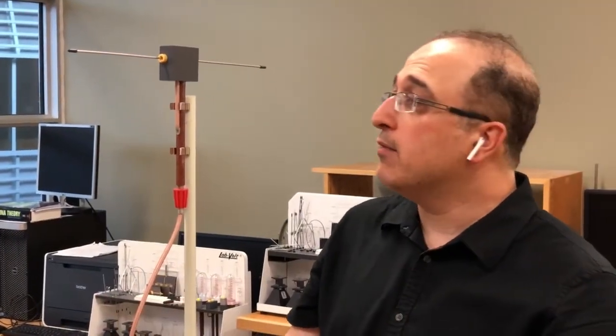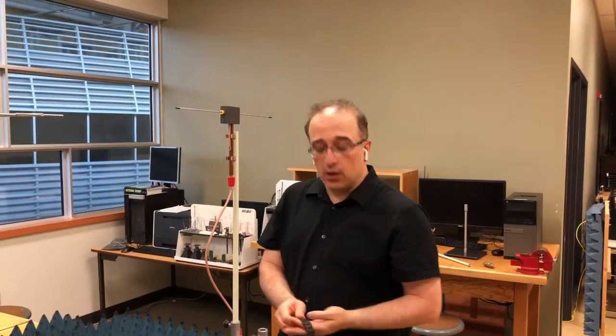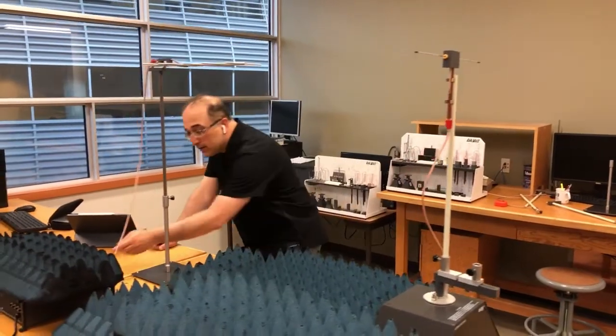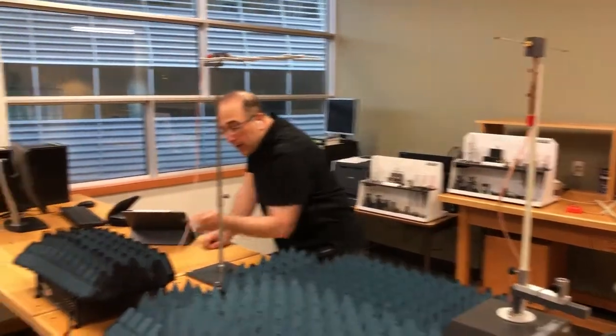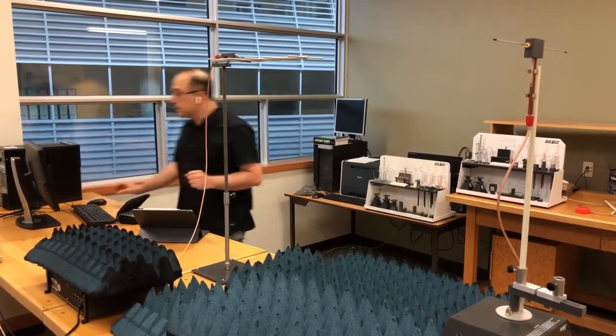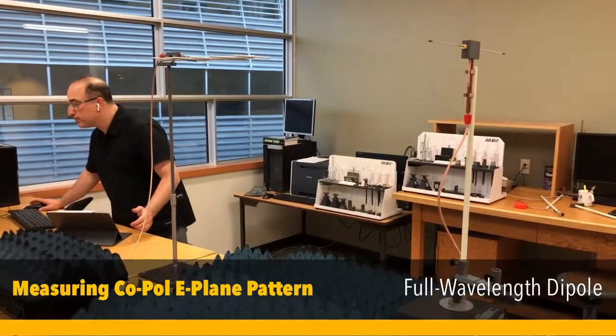And as you see, this is still the setup for E-plane measurement, and we're going to go ahead and perform E-plane cut measurements for this dipole antenna. Similar to everything we had so far, I'm going to turn on the RF power at 1 gigahertz and start the acquisition on the system.